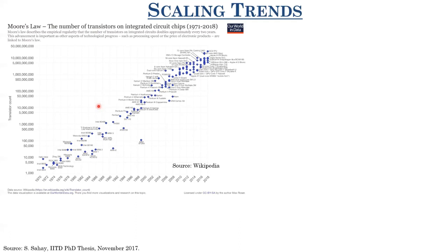So you scale the device, your physical dimensions reduce, your current increases, and your parasitic capacitance reduces, because capacitance is proportional to the area, and the area is also reducing. So first your current increases, second your capacitance reduces, and hence the time it takes to charge those capacitances also reduces. So your speed increases.